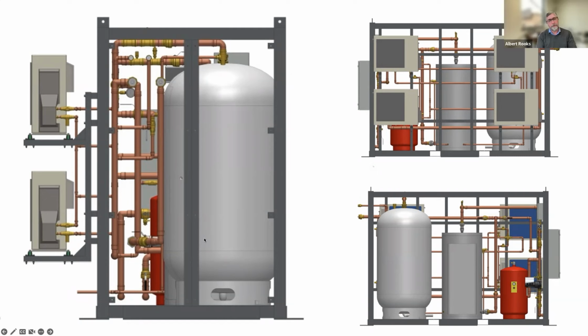That power is given over to the heat pumps, and there's a controller box that's kind of hard to see in the upper right-hand corner of that lower right-hand picture. And the plant's just ready to start up. It can drop on site. The installing contractor is responsible for hooking up 3 water pipes, and the electrician is responsible for landing 3-phase power in this case. Then a factory trained technician shows up on site and starts the plant up.